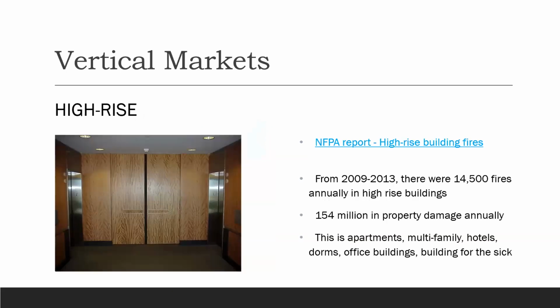Now, of course, high-rise buildings are going to be subject to a lot of fires. Typically, they're going to be multi-use, with multiple vertical openings like your elevator shafts and your stairwells. It's important to note that less than 75 feet might need it, depending if it's a rated corridor. Remember, we talked about that earlier. But when people are sleeping, there are those extra provisions. But with high-rise, you're going to have those really large vertical openings.